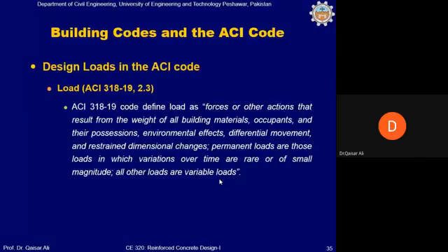It means dead load is the self-weight of the structure and any other material which is fixed to the structure for a long time. For example, flooring on the slab, marble flooring on the slab, and other fixtures which will stay for a long time on the structure will be called dead loads. And live loads will be those loads whose position and magnitude will vary with time. For example, in a school, college, or university classroom, the load of the students will be live load, and the self-weight of the classroom slab, beams, and columns will be dead load.